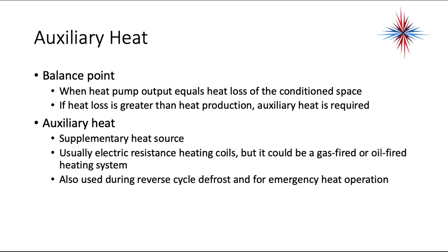So every heat pump has auxiliary heat. It's building code. So when the heat pump output equals the heat loss of the conditioned space, we have to bring on auxiliary heat. That's our balance point. If the heat loss is greater than heat production, auxiliary heat is required.